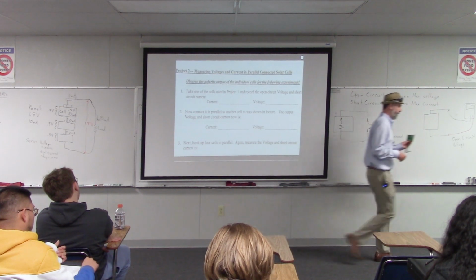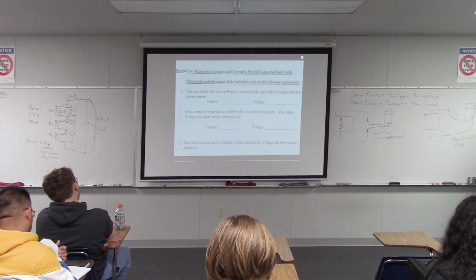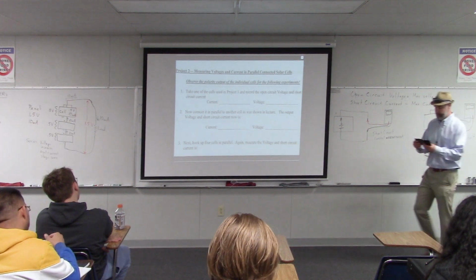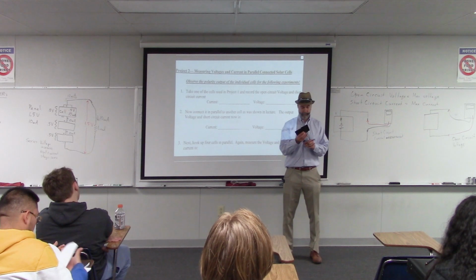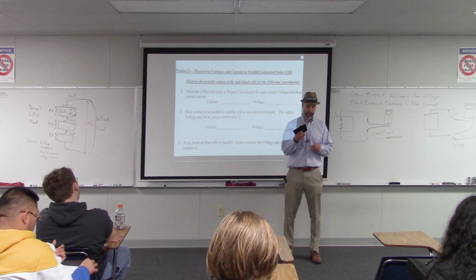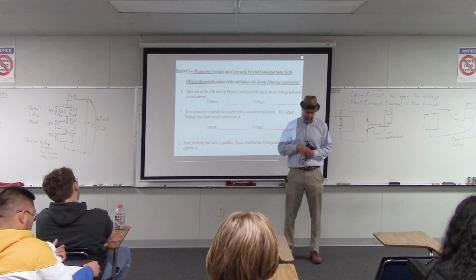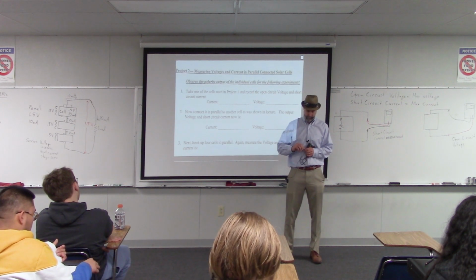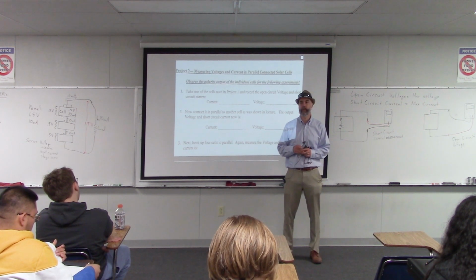So that's all you do to connect the panels in parallel. If you wanted to connect 3 panels in parallel, you would do the same thing, but now you would take all 3 red wires and twist them together, and all 3 black wires and twist them together, okay? And then that's how you would connect these 3 panels in parallel. So any questions about that? Okay.